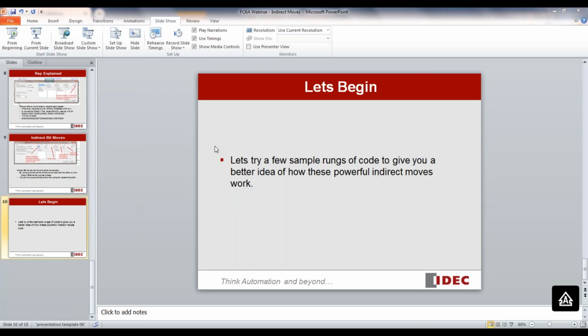One example of an indirect move I used: I had a palletizer when I worked at Clorox. Each box was represented by one word. In that word, there were bits that were on and off that performed functions to position the box on a layer, on a pallet sheet.